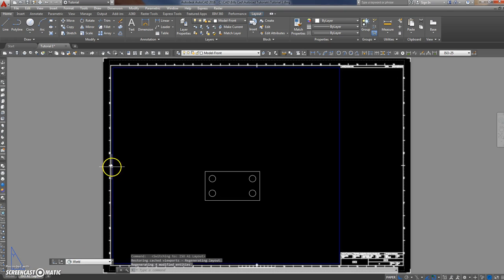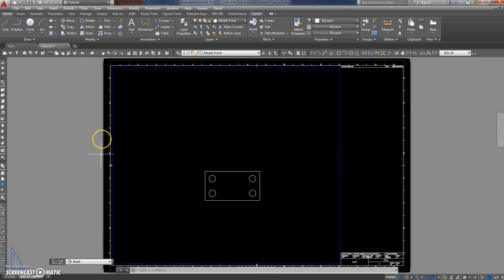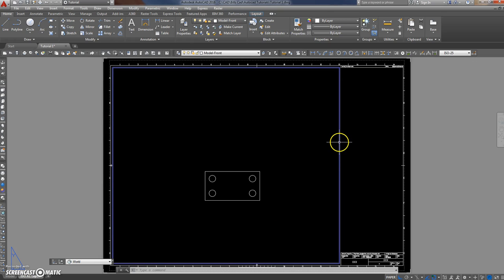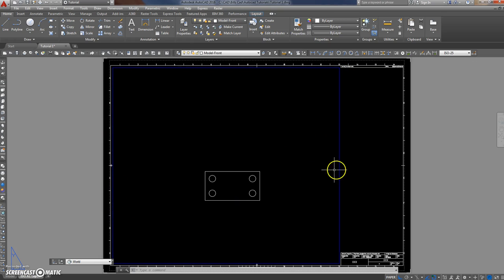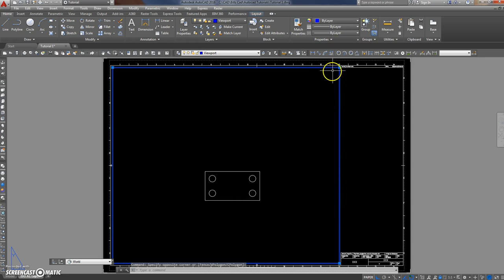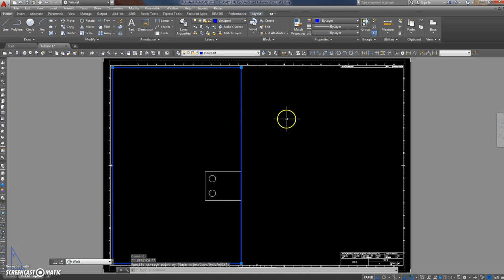Now we come out into our drawing. In this drawing here, think of everything as one-to-one. So this viewport is like a hole that's been cut in paper space. And I'll demonstrate that. There's the hole that's been cut in paper space. It's a look into the world of the model. So there, we're in paper space now, there it is there. But there's the model. We can see into our model that we have done.